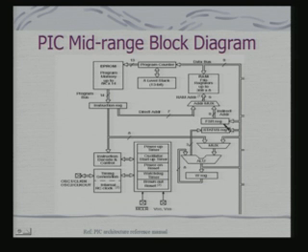And there is also a provision for indirect addressing. Now, how does the indirect addressing take place? Here, conceptually, I select a register, okay, and from that register I come to what is called the FSR register, and from the FSR register I generate the indirect address. It is a slightly complex process. We shall come to exactly the mechanism which is used for indirect addressing when we discuss the instruction set of the processor. So, at least from this architecture, what is straightforward is that I support immediate addressing, direct addressing, and indirect addressing, and primarily my operations are using this RAM, and this RAM is nothing but the same register bank of a RISC processor.